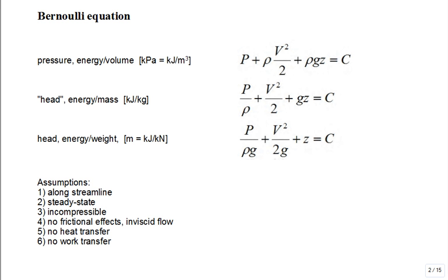This is a summary of the material that we covered last time. Here's one way to write Bernoulli's equation. Here's another way to write the same equation. Here's another way to write it. There are three ways that I would ask that you become very familiar with. Why? Because they're helpful. So one, you can see from this term that it's written in terms of pressure. All of these terms have units of pressure.